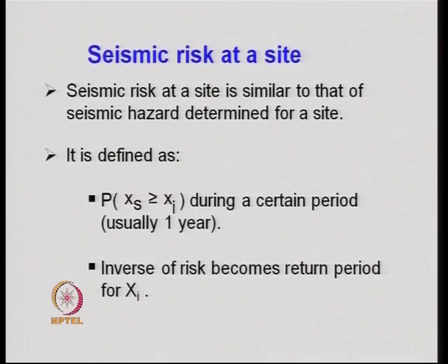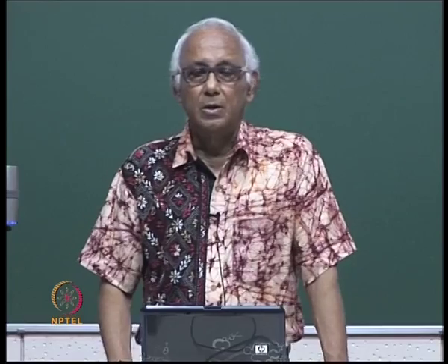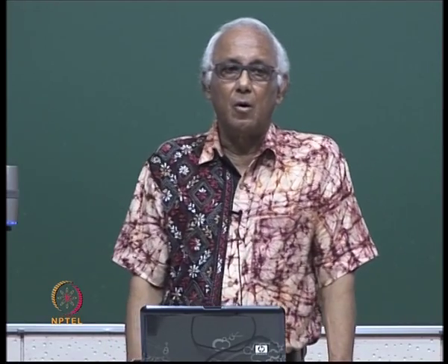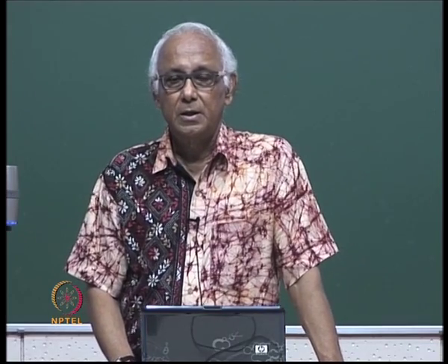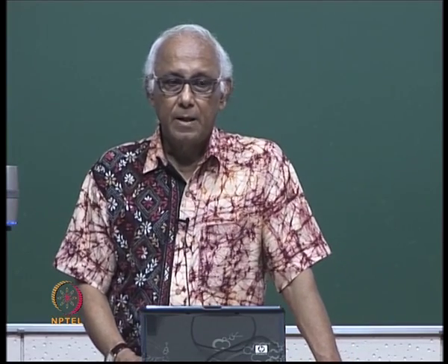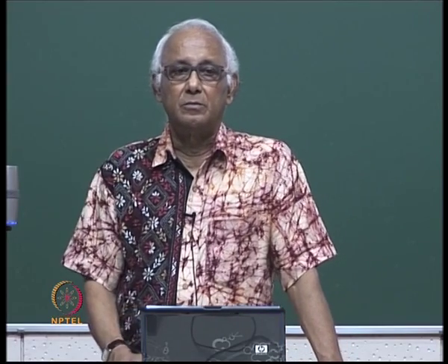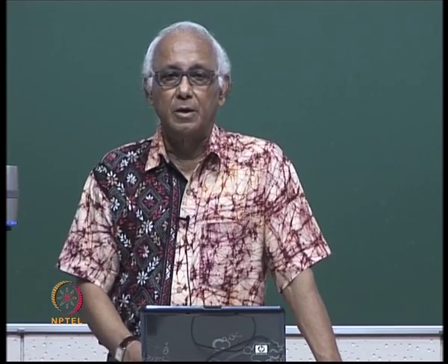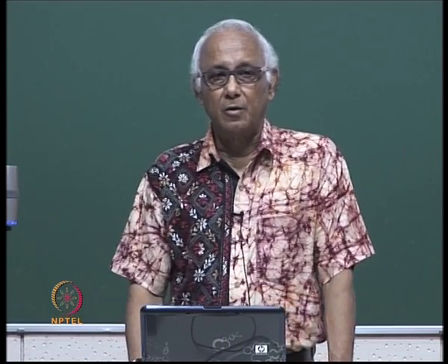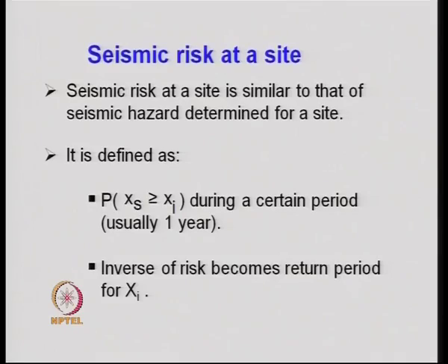So, therefore, given the seismic hazard curve, one can find out the probability of occurrence of just one event and exceedance of at least one event, and given the probability of exceedance for the earthquake for a given period, one can find out the average rate of exceedance, the value of lambda that you have calculated in the second problem.